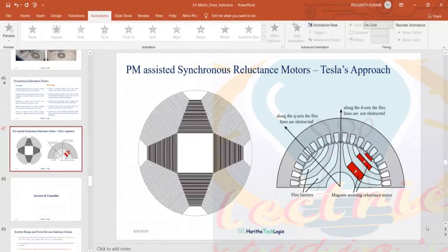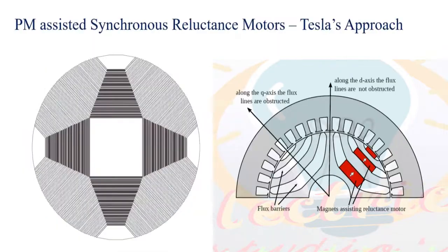That is all about the 3-4 motors, guys. I've briefly covered the 4 motors and their pluses and minuses. Most manufacturers, about 90% of electric vehicle manufacturers, are using permanent magnet synchronous motors for electric cars and bus applications. Very few companies use induction motors. Audi is using an induction motor; even Audi was using PMSM and later went to an induction motor. And Tesla is using an induction motor and the synchronous reluctance motor. They are newly joining. So like this, new technologies are coming on the motor side.